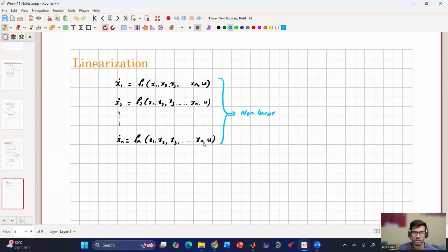So in this way, if we have more operating points, we'll have to design the controller for each of them, and this is called the gain scheduling method, which is also what sir has mentioned. So they will have different gains for different operating points based on the state variables. If the state variables are close to one operating point, they'll have one set of gains. If they're moving towards another operating point, they'll have a different set of gains.